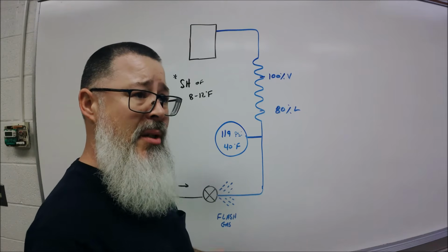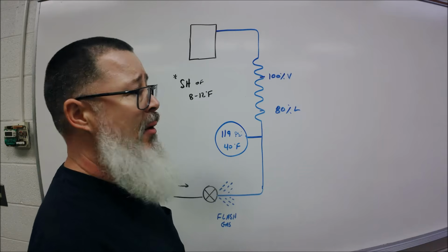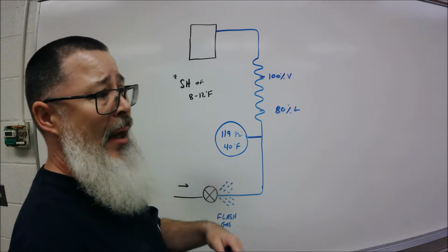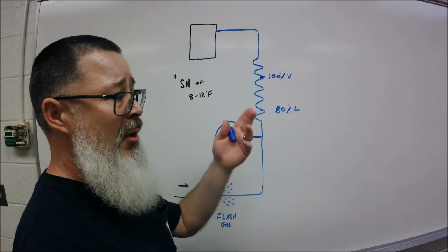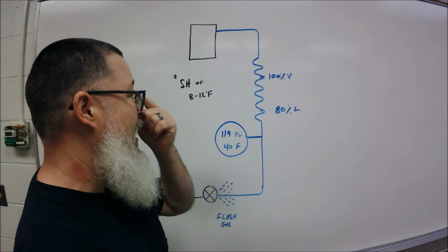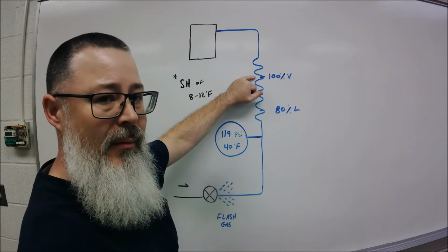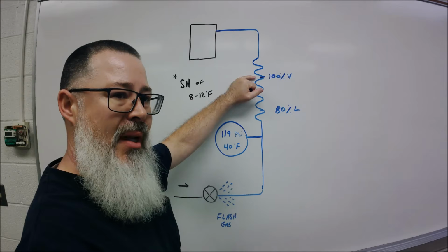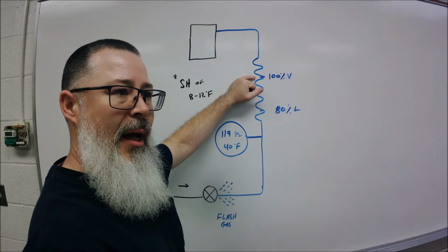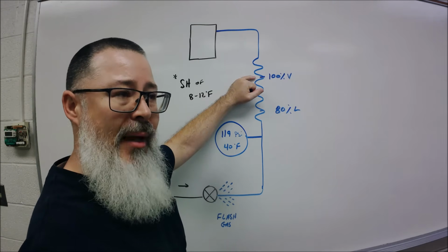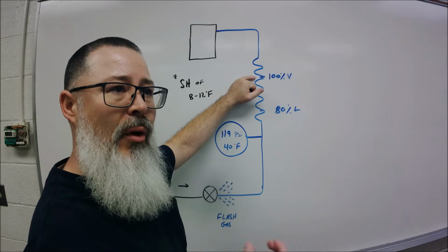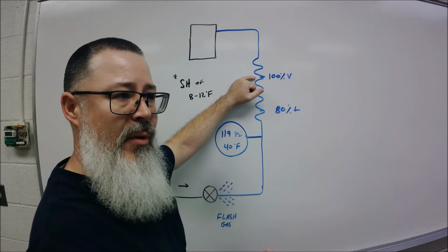It's absorbed the BTUs that's needed for the system, whatever it's rated for: 1 ton, 2 tons, 10 tons, what have you. At this point, when we have finished the change of state, the pressure temperature chart does not apply anymore. There's no more liquid there. We're not a mixture of the states of refrigerant.